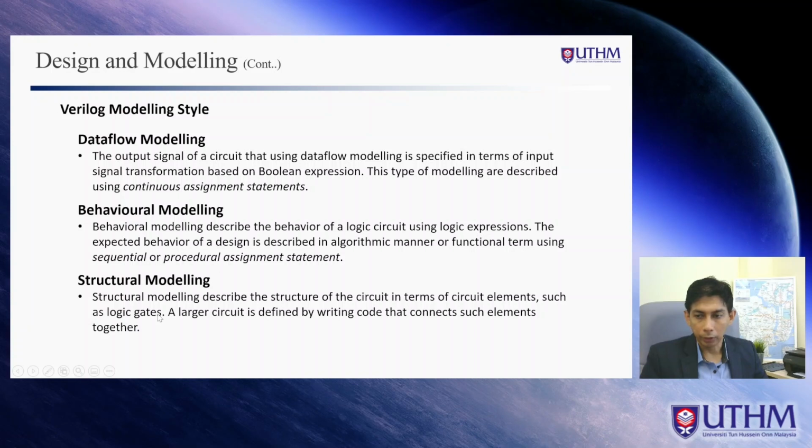And also we have structural modeling, where we can describe or model our digital circuit using the structure of the circuit, where we need to have, of course, the structure or the schematic of the circuit, because we describe the structure based on the connection of the circuit, what gates we have and how the gates are connected to each other, right? So that's called structural modeling.